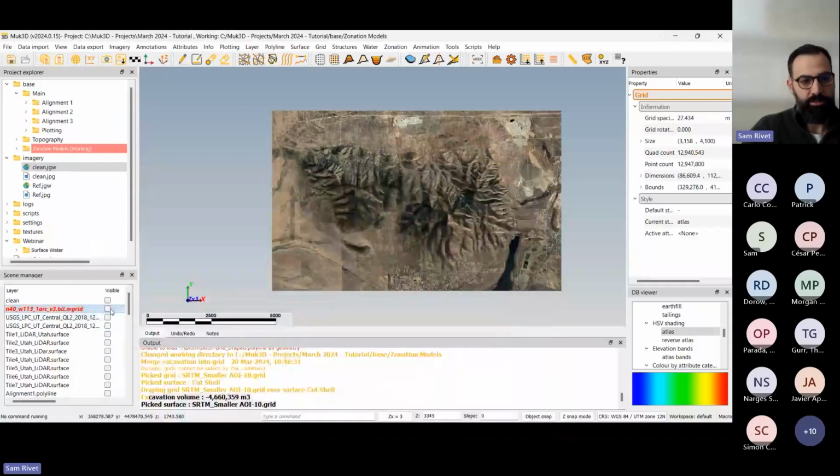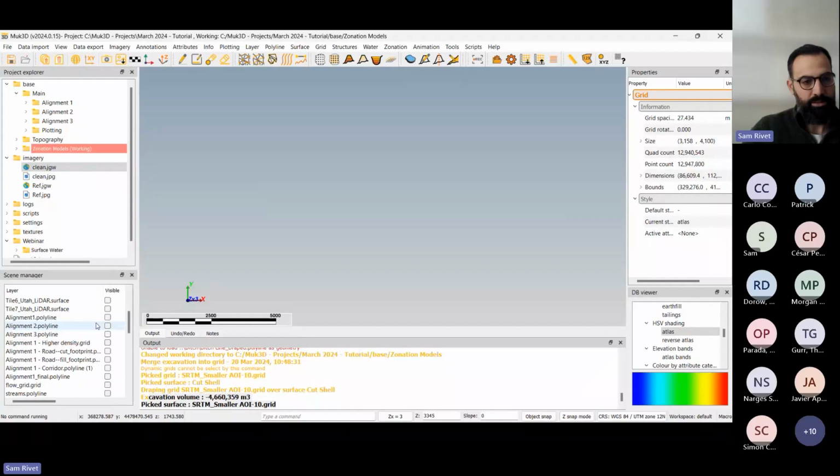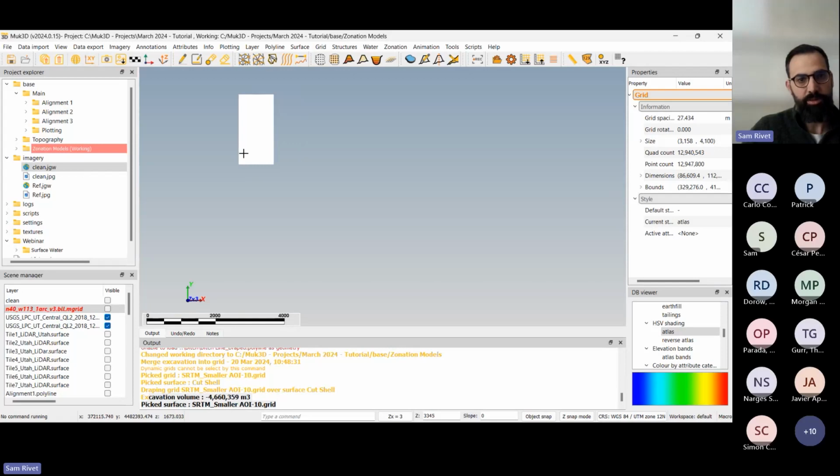And then once again, you can bring them in. You can just save them directly into your formation folder, and then bring in these point cloud files. So you can't really see what they are right now because we haven't triangulated them yet, but they're coming in 1 square kilometer pieces. So if you're going to try to cover a huge area, it is going to take some time. For example, the SRTM data came in like a 5,000 square kilometer chunk. This is coming in 1 square kilometers, but there's a lot more data here.